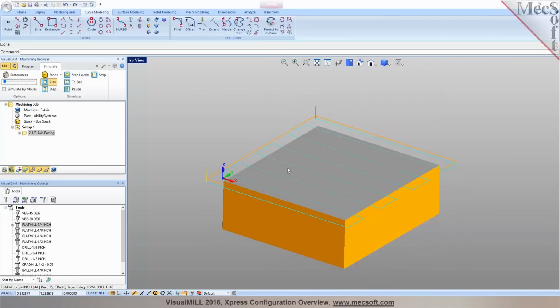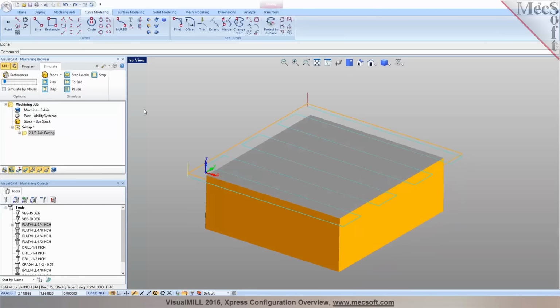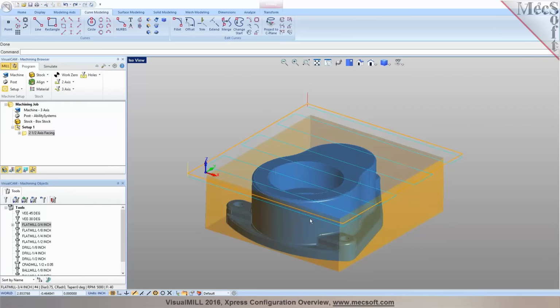Now, starting with the standard configuration, you'll also have the option to use the advanced simulation engine, which is the polygonal simulation module, which basically gives you a much finer resolution on the simulation. As you may notice, some artifacts would show up in Z levels with the voxel model, as the resolution of the stock model is not very fine with the voxel simulation model. And we'll go with that as we program additional features on this part.